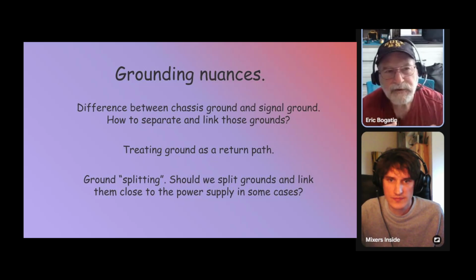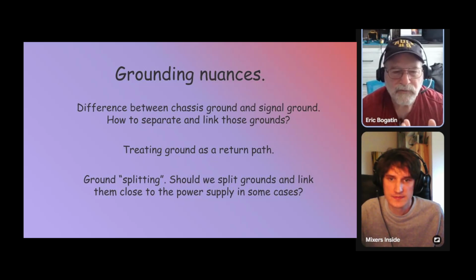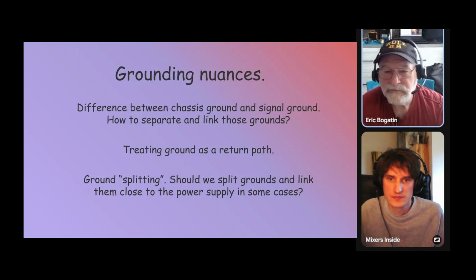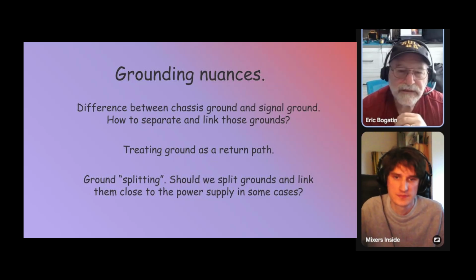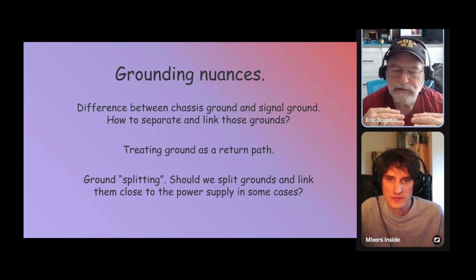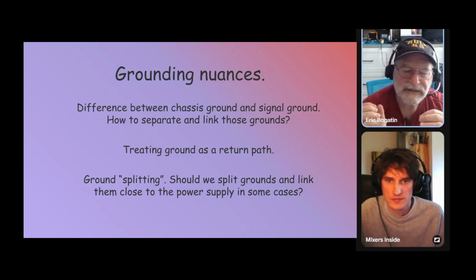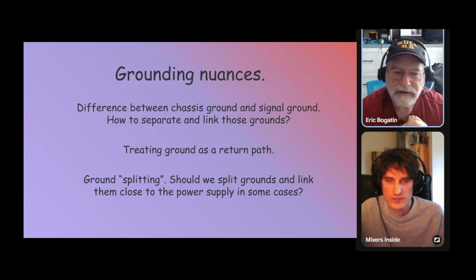Typical resistance in the ground plane for that return current is about a square or two of resistance, and in 1 ounce copper on a board, that's about half to 1 milliohm, depending on the thickness of the copper. So there could easily be 1 or 2 milliohms of DC resistance in that return path conductor, that ground conductor.